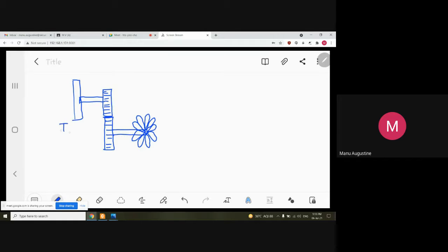Let us say this is I1. Let us say the inertia of the driving gear is IG1, and the driven gear is IG2. And obviously the impeller of the pump looks like it has got all the fan, the fins and all, but for your case, you will simply put an equivalent rotor.